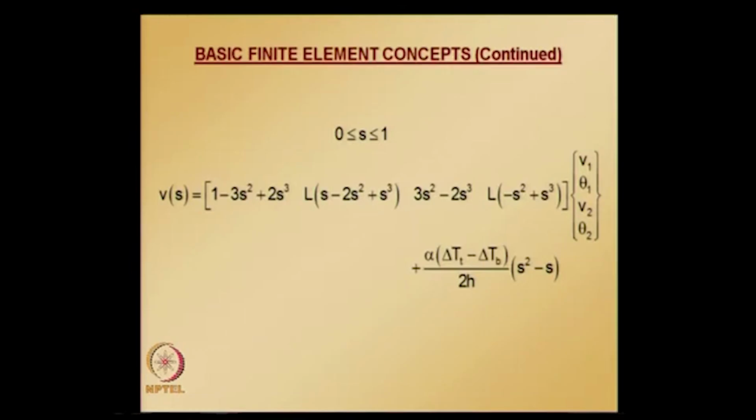So displacement at the ends, at s equal to 0 and s equal to 1, is 0. Applying the condition that transverse displacement v is equal to 0 at s equal to 1 and s equal to 0, and integrating the curvature equation twice, we get the fixed end solution, which acts like a correction term to the transverse displacement obtained from finite element interpolation.